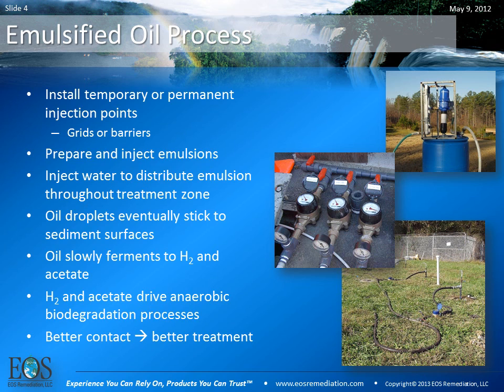What happens in the subsurface is that the oil droplets will eventually stick to the sediment surfaces, and they will ferment over time, releasing hydrogen and acetate, which are the drivers for the reductive dechlorination process for chlorinated solvents. The goal here, and the goal of this design tool that I'll be speaking about, is to achieve better contact, which translates directly to better treatment.